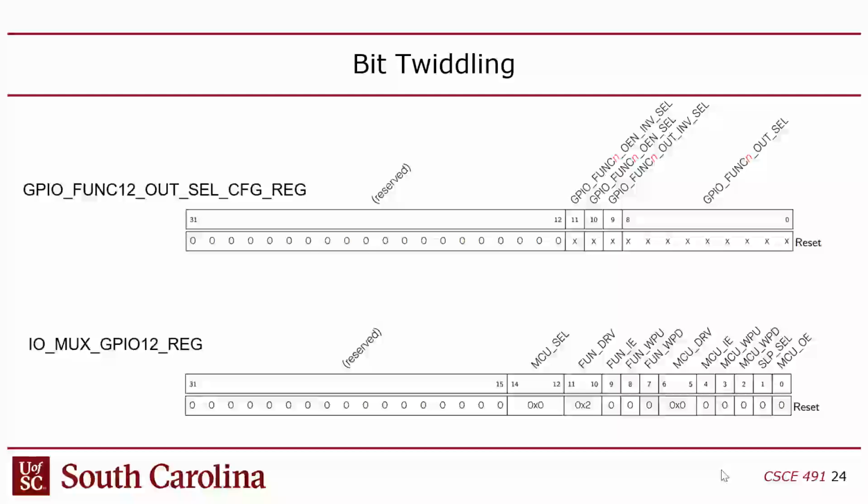And also you'll notice that a lot of these registers have bit fields that are marked reserved, meaning that you're not supposed to write to them, and you're not supposed to read from them and interpret them in any way either. They're just reserved. And that happens a lot when you have 32 bits. Like in the Arduino, the ATmega 328, because there were 8-bit registers, there weren't a lot of reserved bits in there. But in the 32-bit processors, there tend to be a lot of reserved bits.